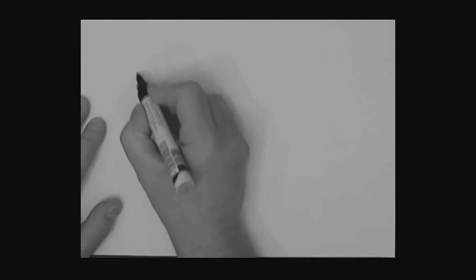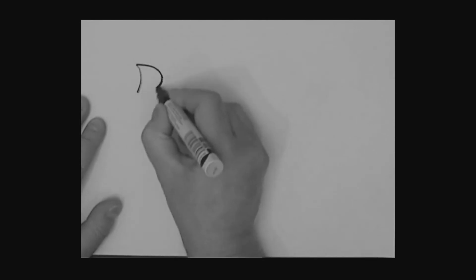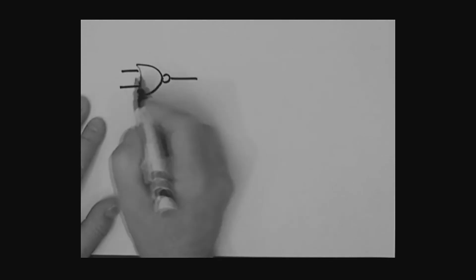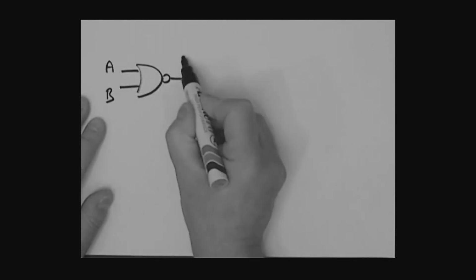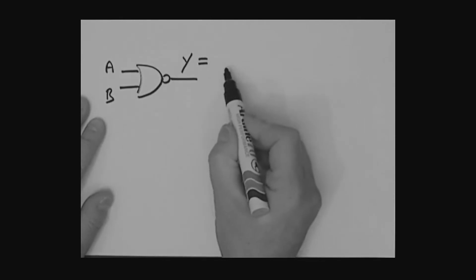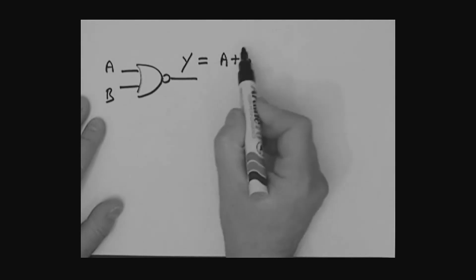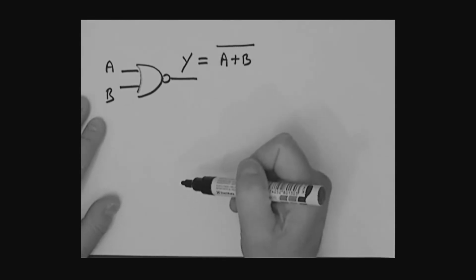Okay, that was the case where we built our SR latch with NOR gates. These are called cross-coupled NOR gates, and we analyzed how that worked. Now, we could use an alternative approach, okay? So let's look at this. All right, now for a moment, let's once again draw the NOR gate. Here is our NOR gate, all right? And supposing for a moment I had inputs A and B. There's our output Y. Well, what is the expression for Y? Yeah, Y is A or B, with a bar over the whole thing. That's the NOR function, isn't it?